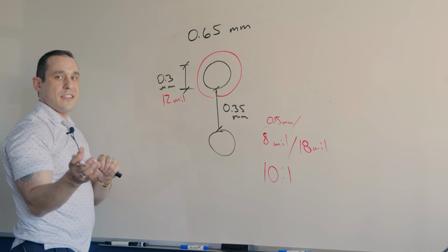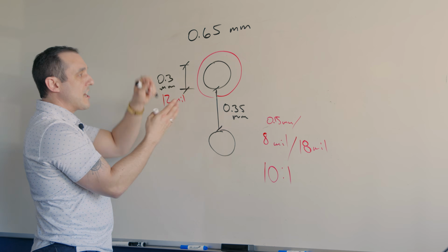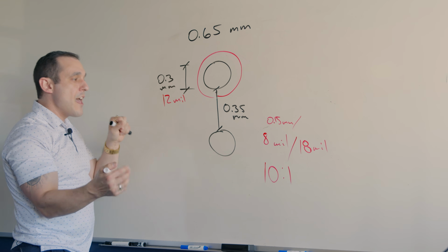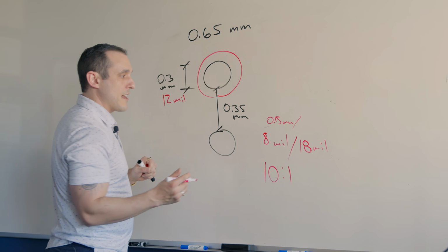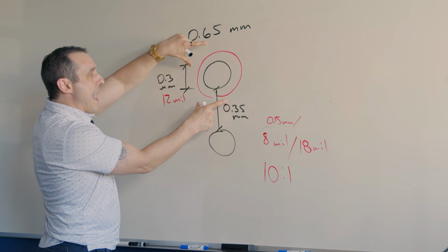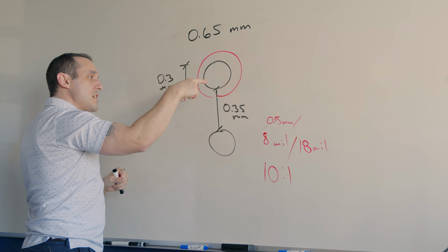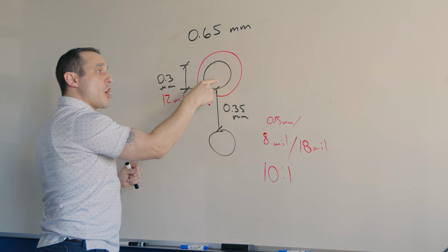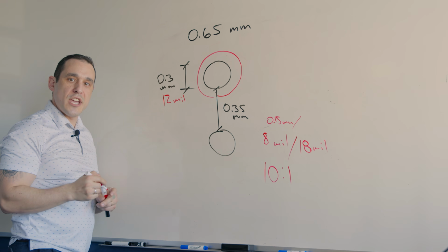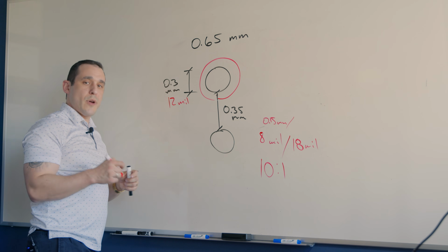So you can already see that when you have these thicker boards with a lot of pins on a very dense BGA, that's forcing you to use these larger mechanical drills. And that increases the pad size that's required for these vias around this exposed copper requirement based on this BGA pitch size. So what should we do in this situation?